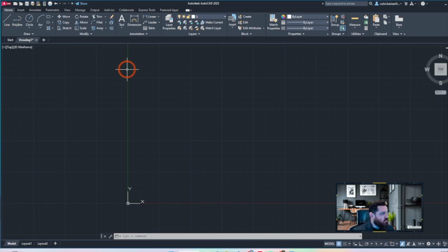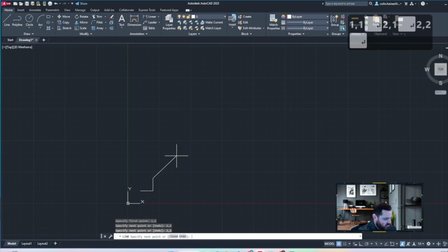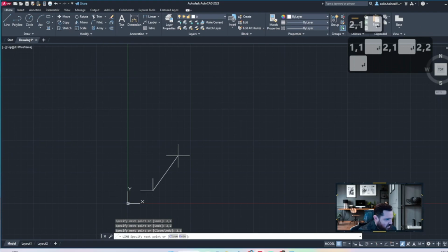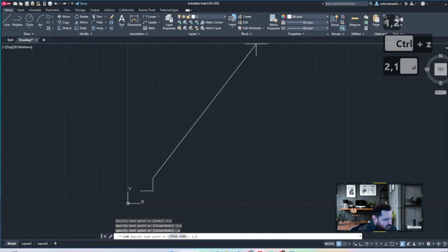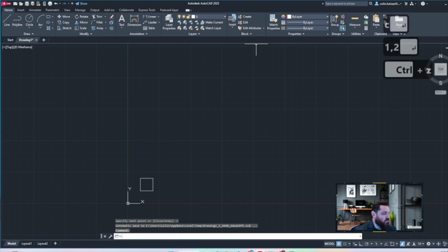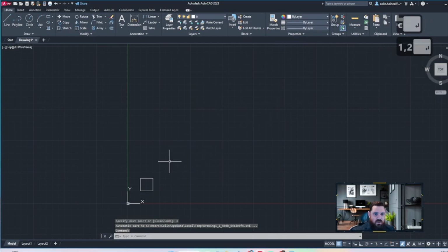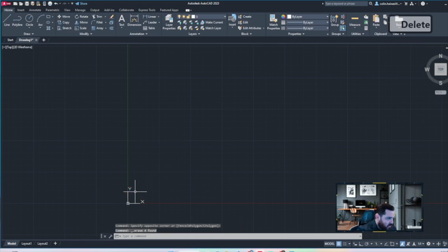So, last time around, we did use the line tool quite a bit, and we would draw little rectangles with that. So we would go 1, 1, enter, 2, 1, enter, 2, 2, enter, and 2, 1, and, whoops, sorry. Control Z, 1, 2, and C for close. And as you can see there, that took a minute. So there must be a quicker way, and there is, and that is simply the rectangle tool.